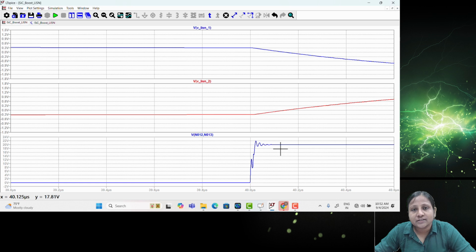see there are oscillations due to parasitic inductance presence in the gate path. And obviously there will be some turn on delay due to the input gate capacitance. And now this input gate capacitance along with the parasitic inductance gives this kind of oscillation. This is like a basic LC network. If you simulate a basic LC network and try to analyze the network with RLC, which is having the pulse kind of input, you will get this kind of behavior, right? Okay, so this is the part.